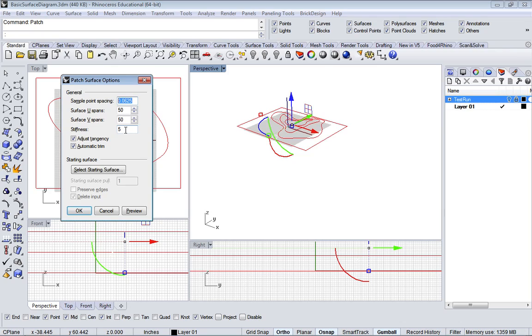I've experimented a little bit, and what I found is that, because of the scale, you want to think about the scale, and we can always look at our little dots here. To be more accurate and follow these contour lines more closely, I need to make sure that the sample spacing is small enough. If it's 1, it's going to make big jumps, and it's not going to follow the contours very well. So think about this as resolution, of it going through every little piece of that geometry at that distance and analyzing it for contour.